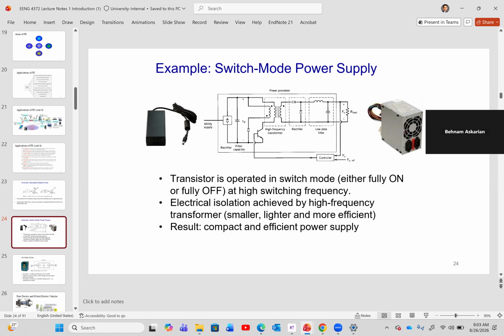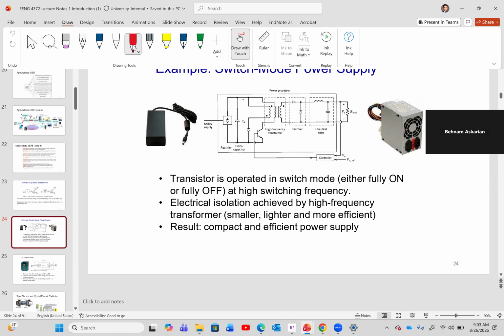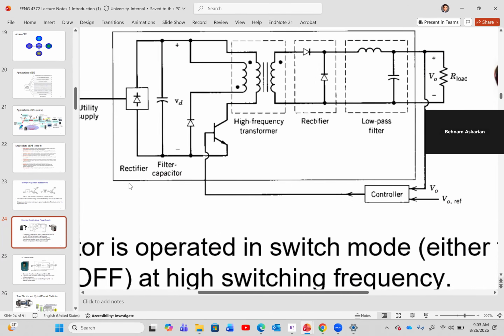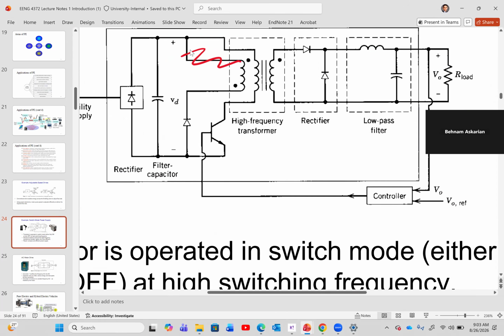Now, the way that they do that, and I opened one, if you open a hairdryer, you can see it in that as well, is that in these new systems, for example, one system that they use is instead of using a transformer in the beginning, and this is a good example that shows it. So the previous systems didn't have this part. You had a transformer, it went from 120 volt directly to 12 volts. And this transformer needed to be huge, okay, if you had high power.